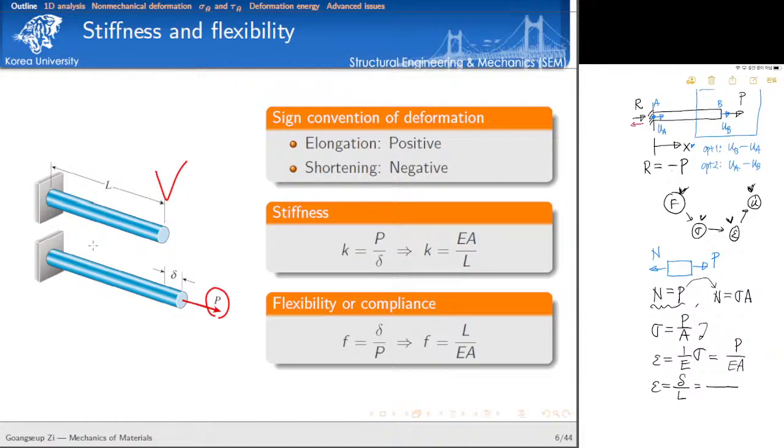So can you explain the reason that you considered option 1 is correct for other students, so that they can understand what you think? So make sure that the elongation, what's the definition of elongation? Elongation is the way of stretch, isn't it, right? The way of stretch. That's why, to get the measure of elongation, we need to subtract UA from UB. Otherwise we cannot get it.